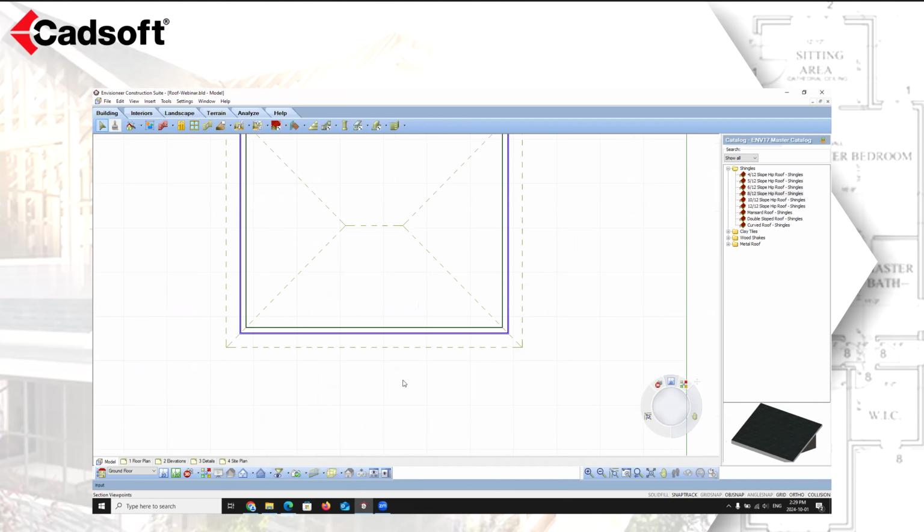So if I want to create a flush gable design, I can do that by creating a couple of breaks in my roof. I like to use the line command. This just gives me a lot of control over where the points are going to be. I usually start with the middle of the wall and I draw in my first line. Let's make this an 8-foot flush gable. So I'm going to go over 4 feet in this direction, and then we're basically going back 8 feet. This gives me 2 points to snap to.